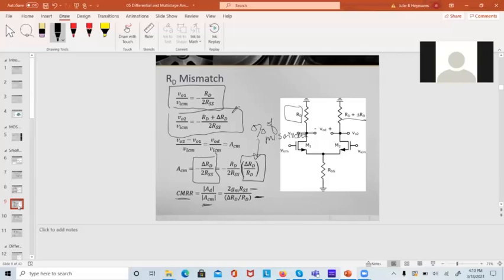I go to bigger devices. They usually don't push the size limit on analog circuits, because you might have several hundred transistors in an analog integrated circuit like an op-amp, so you're not worried about the size of the components as much. A lot of times they're doing things in a 0.18 micrometer process because it's cheaper.